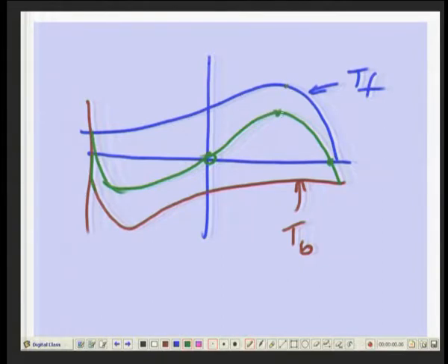You have slightly less torque, because certain negative torque is also being injected at the normal operating point. This has to be compensated, so a single phase motor tends to be rated less compared to a 3 phase motor, because of the additional rotor currents due to the backward field. There is extra rotor heating due to this without producing any useful work.